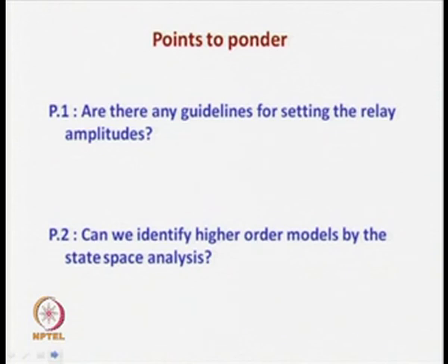If the output is found to be quite noisy, then to overcome the effects of noise, sometimes relay amplitudes are set in such a manner that the actual output waveform can be distinguishable from noises.